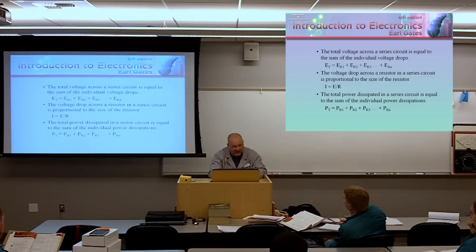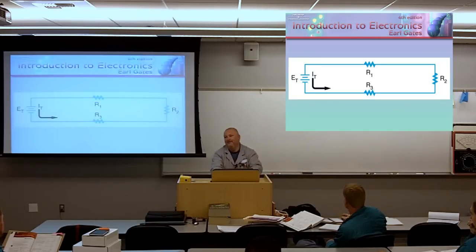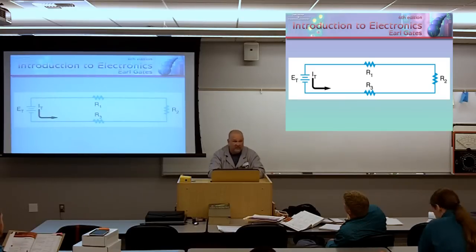Houston, we're going to have a problem. Okay? Those are the most important things. I'm going to have you repeat that back to me in the future. Do not deceive me. Okay? Remember that stuff. The most important thing in a series circuit is current is constant. Why is it constant? It's only got one path to flow, so it better be constant.